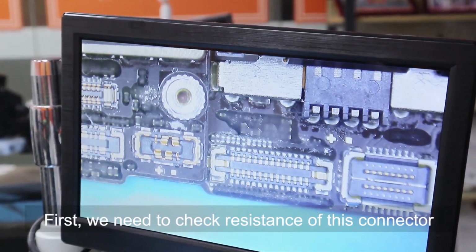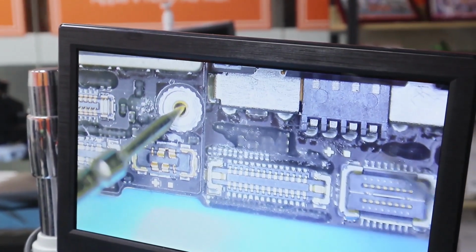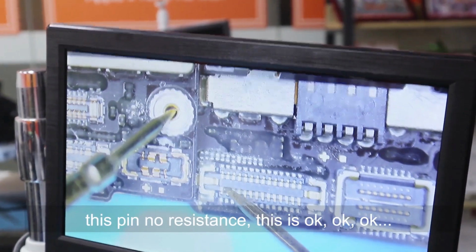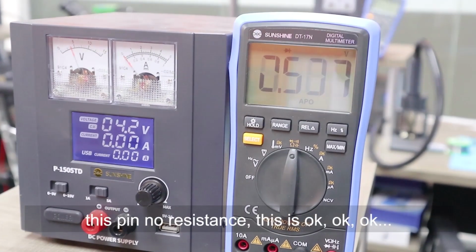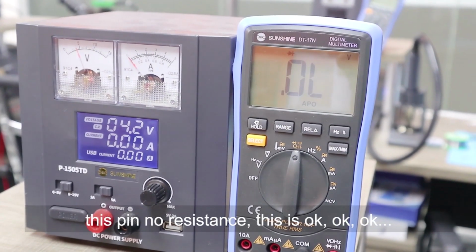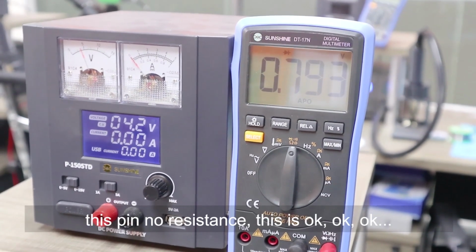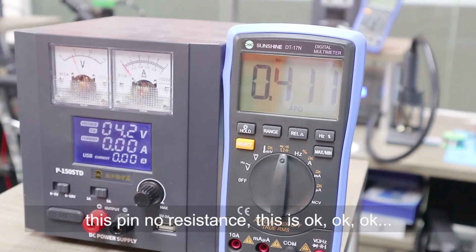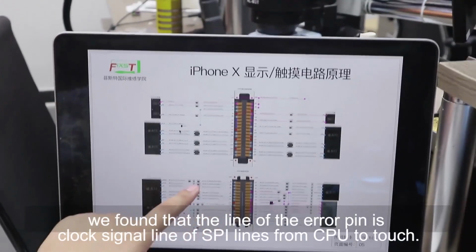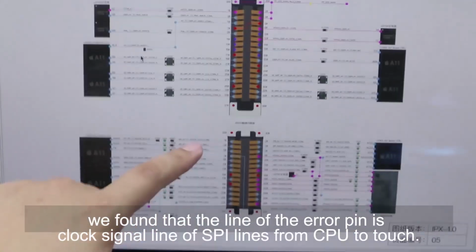First, we need to check the resistance of this connector. This pin has no resistance. Is this okay? Okay. After we check resistance, we found that the line of the affected pins is the clock signal line of the SPI lines from the CPU to touch.